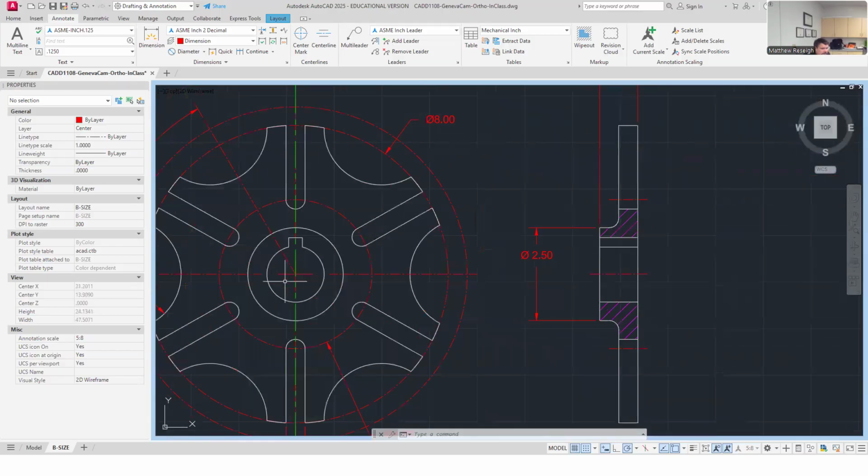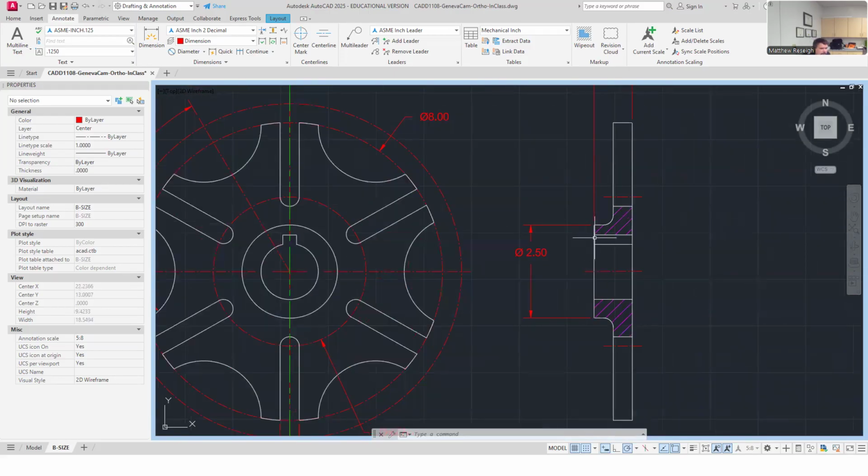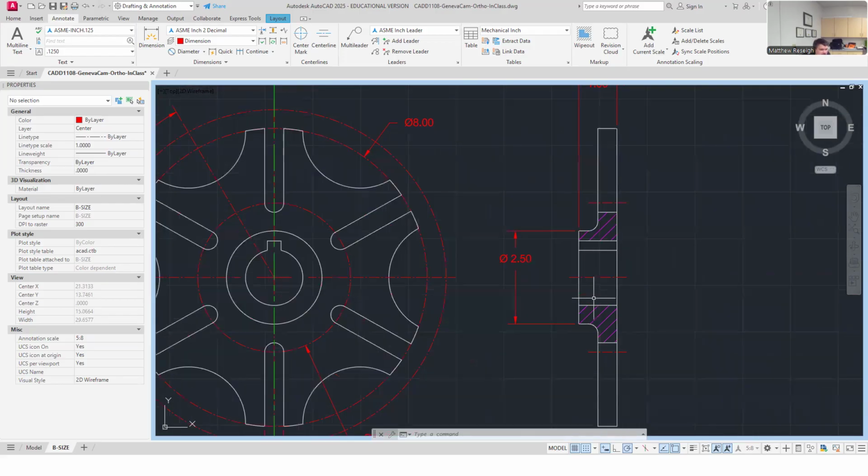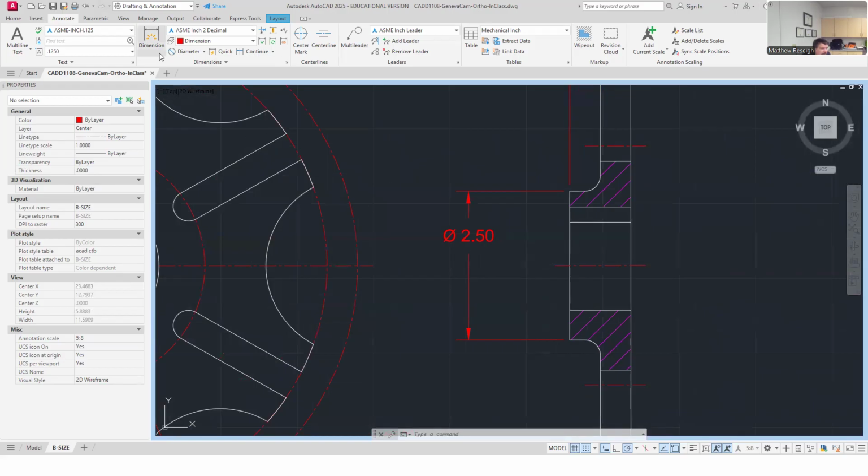So it kind of breaks that rule, so I'm looking at just the inner bore, not the keyway yet. It's another feature, but if the inner bore was solid, if it didn't have a keyway in it, I'd probably size and locate it over here. Its size is also this one. So this is doing dual duty. It's the outer hub and it's the inner hub. They're the same depth. So this one is carrying both of those feature dimensions. And then its diameter, I really can't grab here.